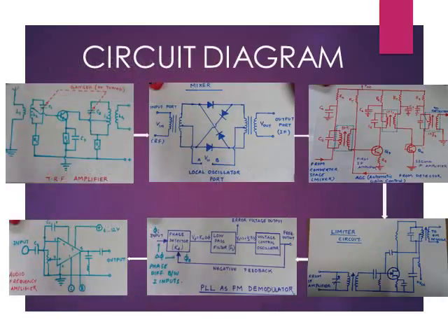Look at a circuit diagram of an FM receiver circuit. Firstly, there is a TRF amplifier, the output of which is fed into the mixer. The output from the mixer is fed into the IF amplifier stages, the output from which is fed into the limiter circuit, which is then demodulated. And after following the audio frequency amplifier stages, it is delivered to the speaker.